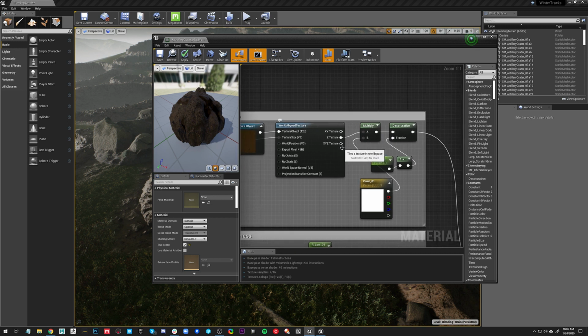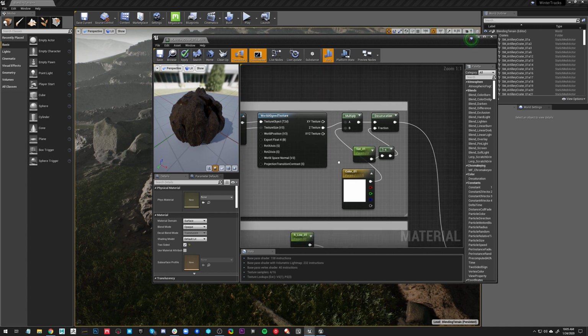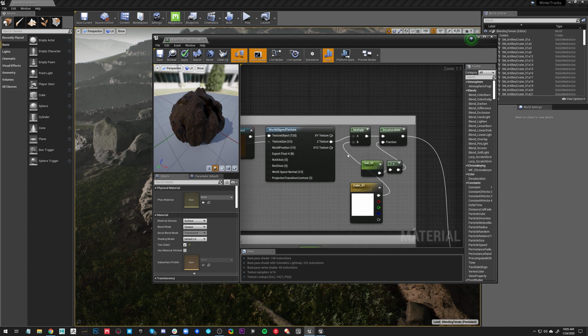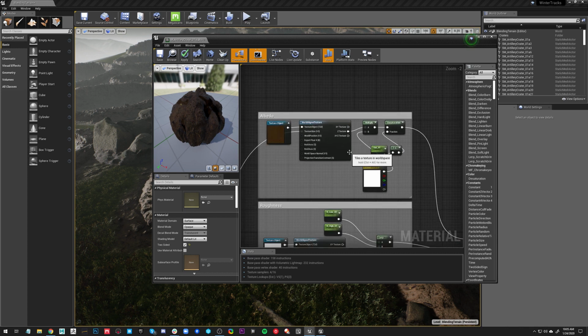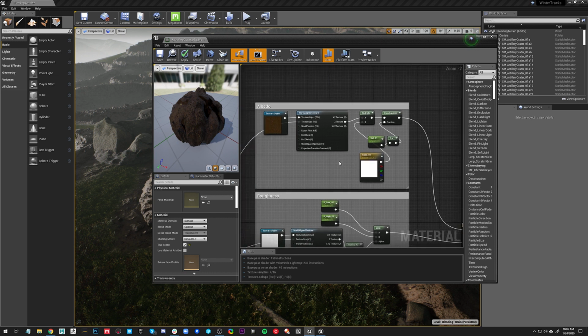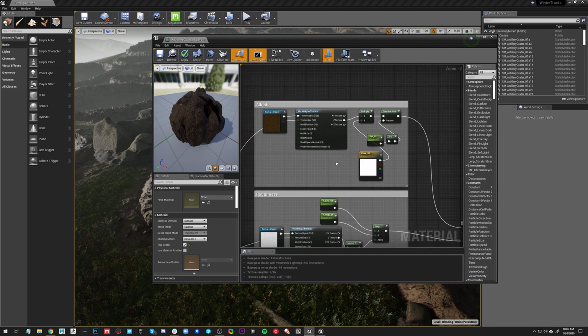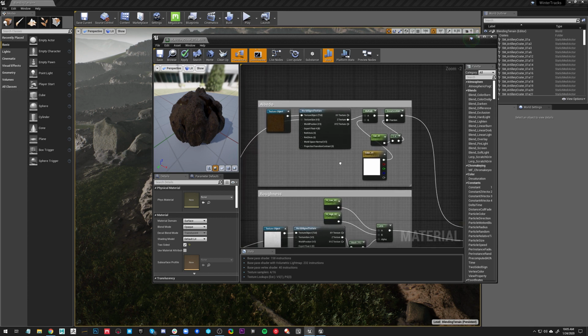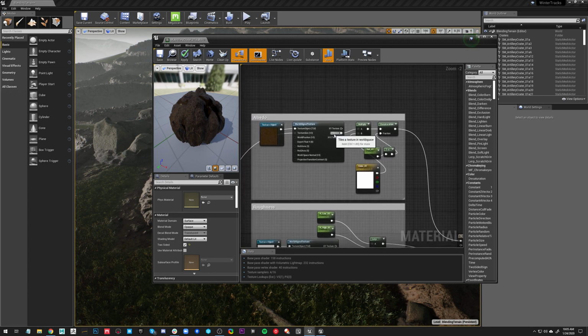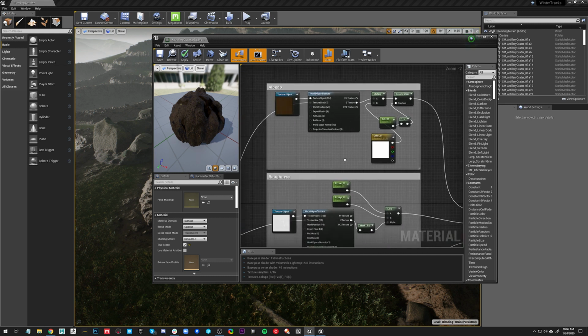And alternatively, you can also do full-blown triplanar projection, which is XYZ texturing. That's going to be really expensive, and you probably should not use that unless you absolutely have to, or if you know you can actually afford to use that, or for portfolio environments, that kind of thing, it's totally okay. But generally speaking, I like to stick to the Z texture because that is the cheapest.